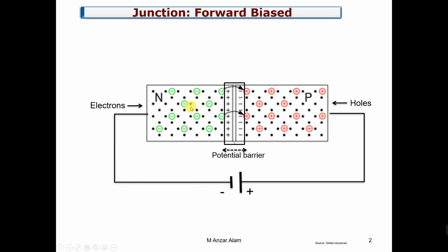Those free electrons will diffuse with the positive charge across the potential barrier, across the junction layer. Similarly, the plus terminal of the external power supply injects holes inside the p terminal. It already has holes, and furthermore these holes will diffuse with the electrons at the edges of the potential barrier, at the edges of this thin layer.